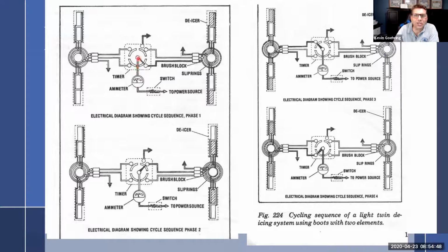So the sequencer, right now it's going to go through here and out. Outboard. Yeah. So right now it's going to go to this side and go outboard, outboard, and it's going to heat up the right prop. And then it's going to come around and I think it comes down here, inboard, inboard. So it's right prop, out, out, in, in, left prop, out, out, and in. And then it comes back around and starts again over here. It's just going to sequence it through like that.